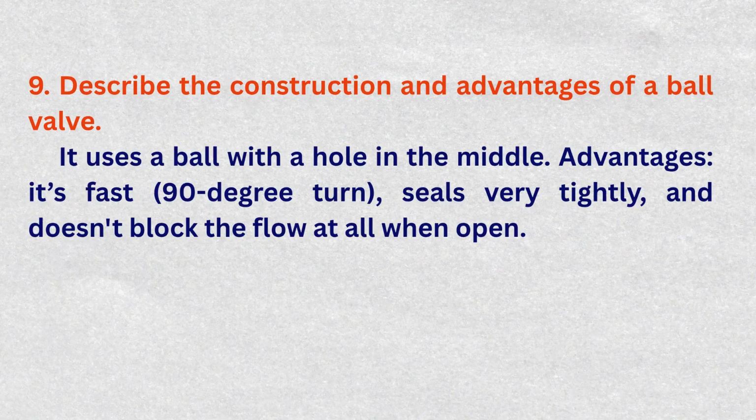Describe the construction and advantages of a ball valve. It uses a ball with a hole in the middle. Advantages: it's fast, 90-degree turn, seals very tightly, and doesn't block the flow at all when open.